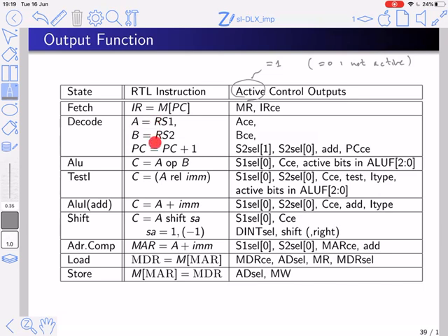So what are these RTL instructions doing here? Well, it's a funny thing. They're not related to decode, but you want to do them just in case, because they might be useful later when you're trying to execute the instruction. So for example, your default is that the next instruction to be executed resides in the address which is 1 plus the current address.